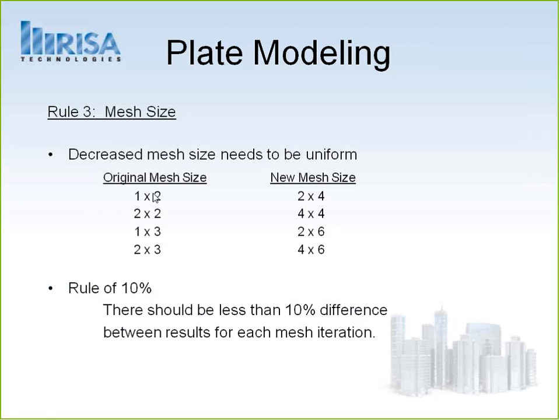But if you start to see more than 10% of change, and when I say change, the best measure is your deflected shape. That's what I stick with. I always look at that deflected shape, and that's where I stop.